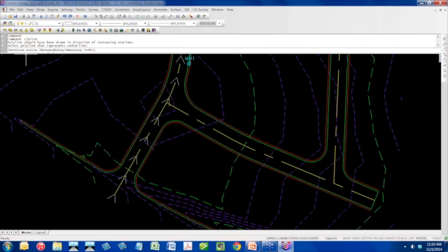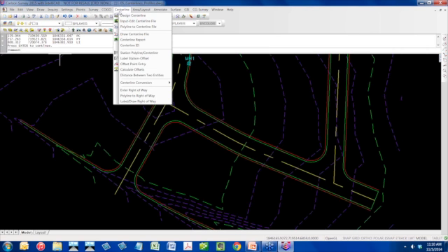So if the polyline was not drawn the direction I want the stationing to go, I could reverse it from here. For now, we'll just start the beginning station at 0, 0. And it's been done. So that's step one. We've gotten this centerline file defined. Now, if you want to look at that centerline file definition, you can go to Input, Edit, Centerline File.